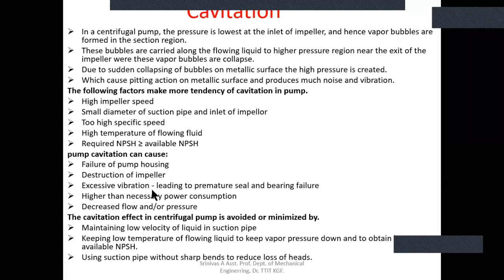This leads to damage in the sealing or bearing, or breakdown takes place, and higher than necessary power consumption, and decreasing flow and pressure because of this cavitation, the water discharge will reduce. Those are the drawbacks.